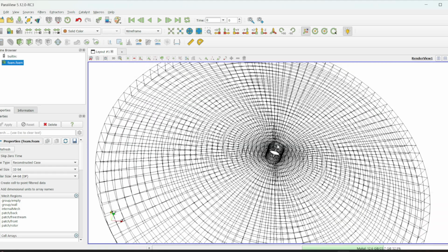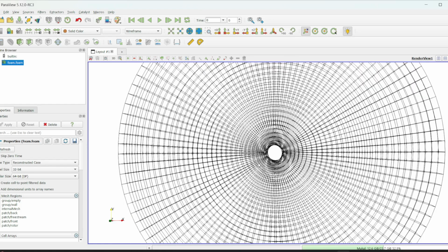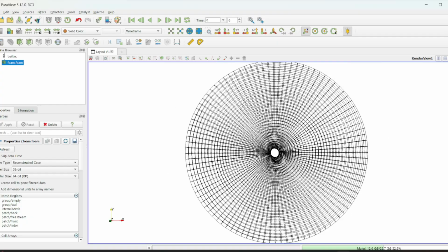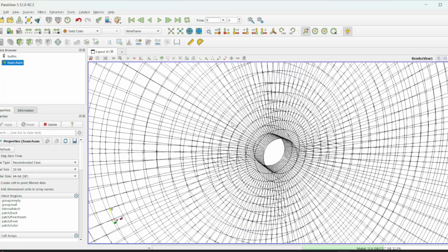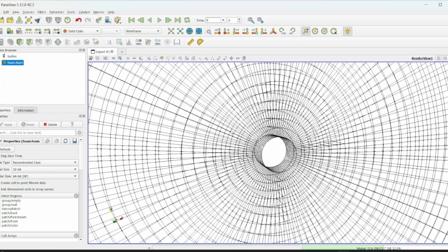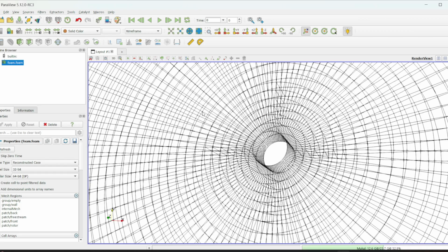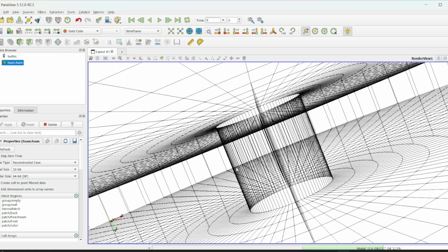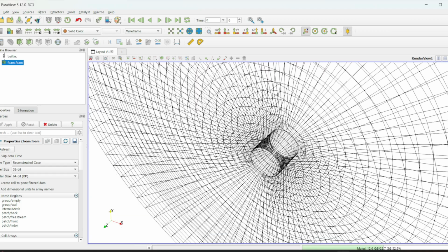If you wanted, you could do it another way: first make a rectangular block mesh, then make the geometry in 3D modelling software, and with the help of snappyHexMesh insert it. So either you do it that way or you can do it this way. This is a very new thing, and I liked it because I have used it for the first time, and it is very nice. You can see what a perfect mesh has been made. No distortion, nothing. It's a very beautiful mesh.